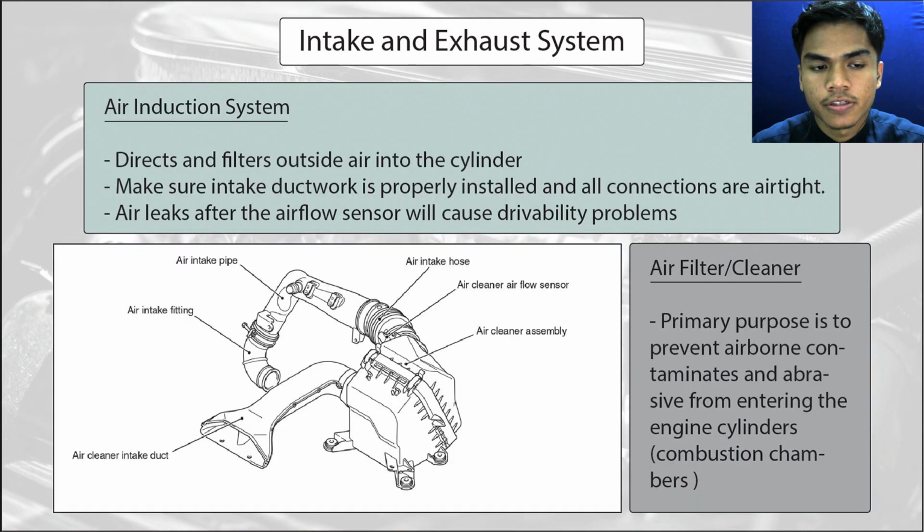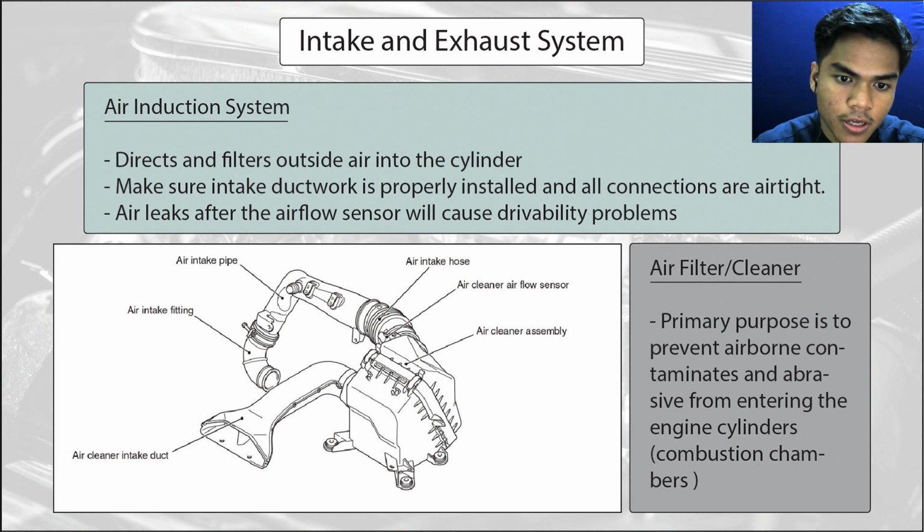Air induction system. The system directs and filters air into the cylinder. It also makes sure the intake ductwork is properly installed and all connections are airtight. Air leaks after the airflow sensor will cause drivability problems.